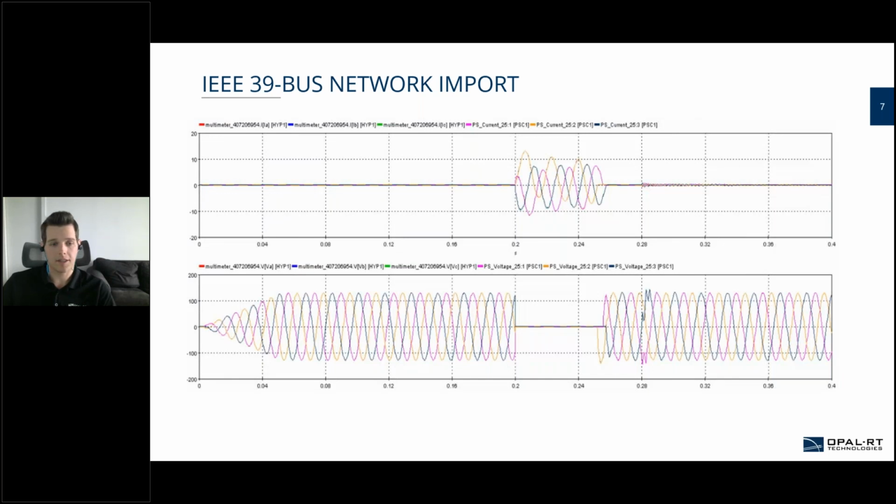So this is a little beside the point here. It's not related to PSCAD, but yes, we can. We really have a detailed PMU model. We support C37.118. You can have virtual PMUs all around your model. I don't remember in the full list of models if we can actually match the PSCAD PMU model so far. Something I would need to check if that was the aim of the question. But we do have a detailed PMU model in HYPERSIM.